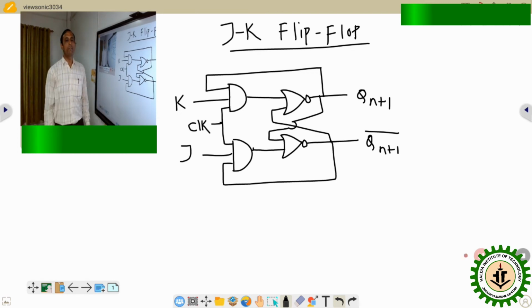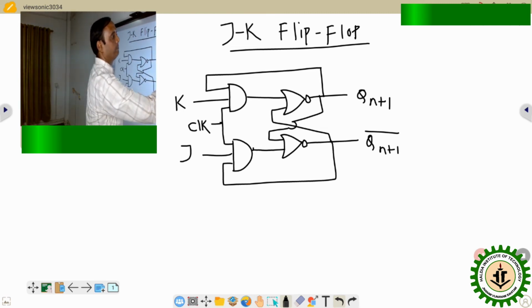So this is the JK flip-flop circuit diagram. Here it is almost the same as the SR flip-flop circuit diagram, only two additional connections are present. That connection is from the output of the NOT logic gate to the input of the AND gate in both the positions. So these connections are additionally made to avoid that problem which occurs in the 1-1 condition in SR flip-flop. So with the help of this circuit, ultimately what we are getting is the characteristics table of JK flip-flop like this.